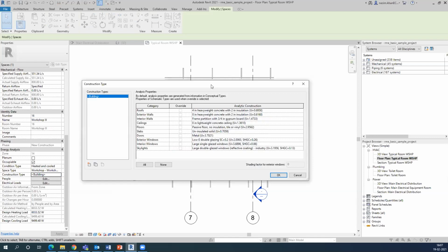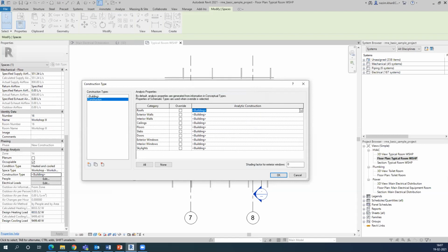The external loads are coming from roofs, exterior walls, interior walls, ceiling, and all the facade area and glazings. These are some of the values that we have, and there are multiple values. A U value for a flat roof is something around 0.2497, and for a different kind of building material used in the building, it is going to give different U values, ranging from 0 point something to 2 point something, as we see here, as the material changes. So that is one of the very important factors while designing the building.